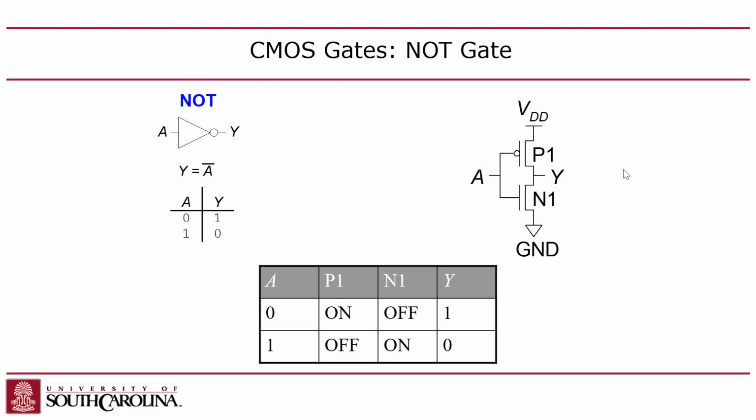It's not mechanical. When they say pull down, it means that it's going to create a low resistance path to ground, right? And this R on, resistance of on, is low, like half an ohm, but the resistance of a transistor that's off is like 10 megaohms. So what you're really doing here is creating a voltage divider, technically.